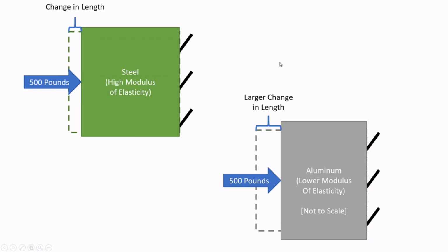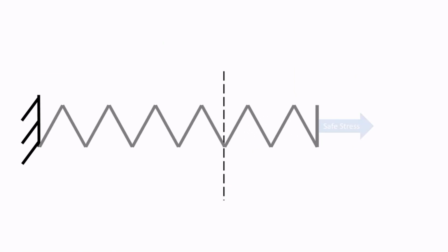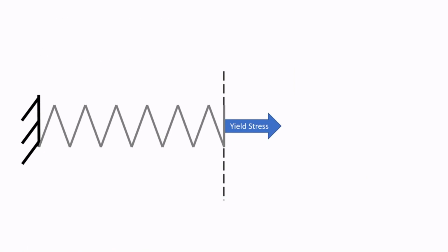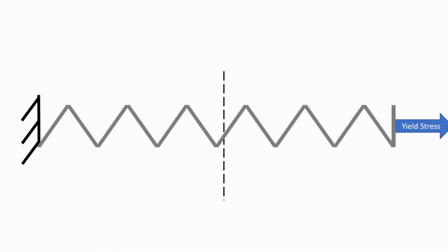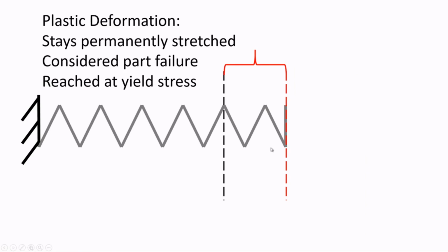Finally, after a certain stress threshold is reached, the material starts experiencing plastic deformation, meaning that releasing the stress will no longer allow the material to return to its original state. Think of how you can pull a spring a little bit, but then when you release the force, it will return to its starting shape. This is because you remained below the yield stress and the material only experienced elastic deformation. However, if you pull too hard and then release the stress, the material stays bent as it's experienced plastic deformation. This threshold is known as the yield stress, and it defines the stress at which the material fails, which is the final important piece for our preliminary introduction.